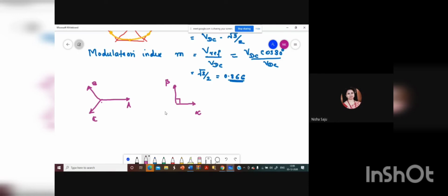And then what you have to do is specify a reference voltage, right? That reference voltage should have a magnitude and phase, and this voltage vector you have to reconstruct on an average by using the 8 possible switching states. So you have to take sampling. How are you doing this sampling? In order to generate the reference voltage vector for a sampling period TS, you have to do the reconstruction. The reconstruction is done by sampling the reference voltage at a given period TS. So for that we are taking this three-phase system to the two-phase system.